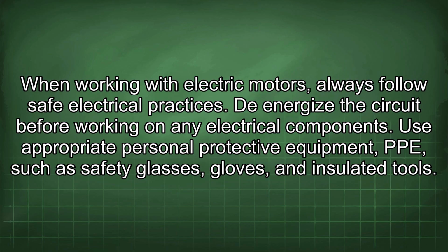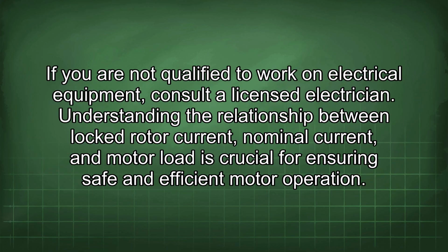When working with electric motors, always follow safe electrical practices. Be sure to de-energize the circuit before working on any electrical components. Use appropriate personal protective equipment, PPE, such as safety glasses, gloves, and insulated tools. If you are not qualified to work on electrical equipment, consult a licensed electrician.